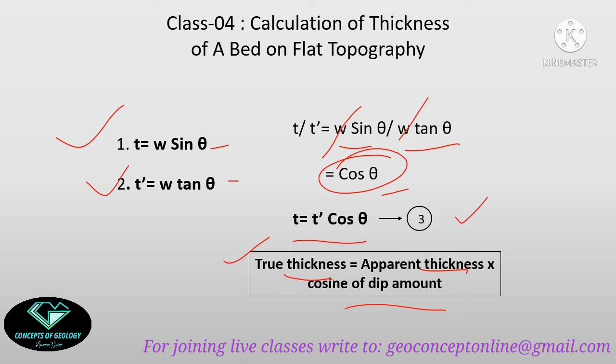You try to memorize, or rather you try to construct this equation in your mind. These equations will help to find out the thickness of a strata or a bed on a flat topography. Always keep it in your mind that these equations are applicable in case of flat topography only. So this is all for today's class.